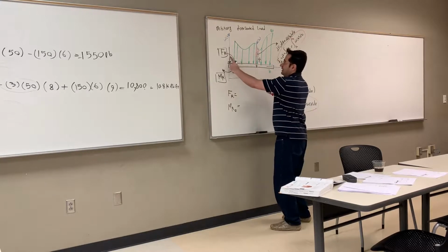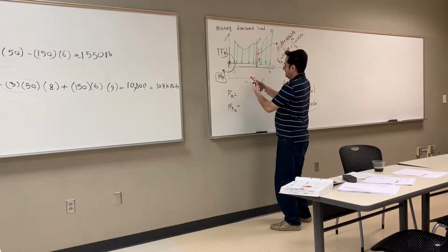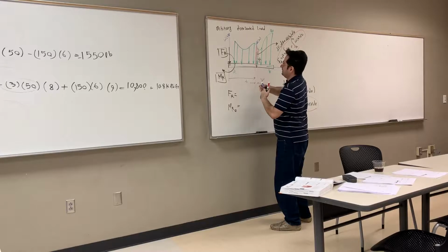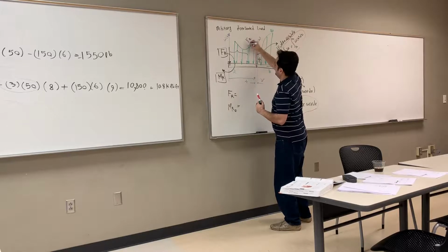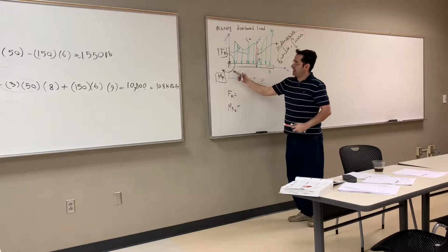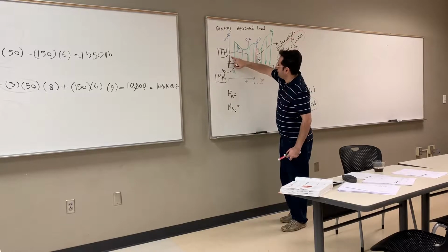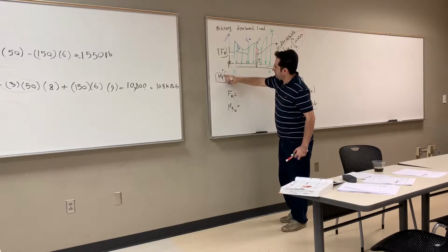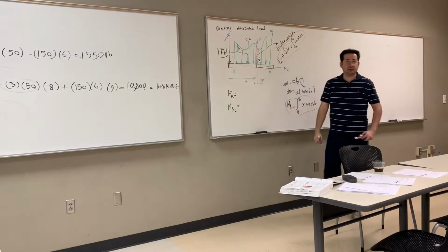So let's do that. Let's move this force to a particular distance like here. At a particular distance like D, let's say. So this is F resultant, move it at D, such that it generates exactly the same moment. So I go ahead and drop this moment because this force moved sideways can generate a moment.